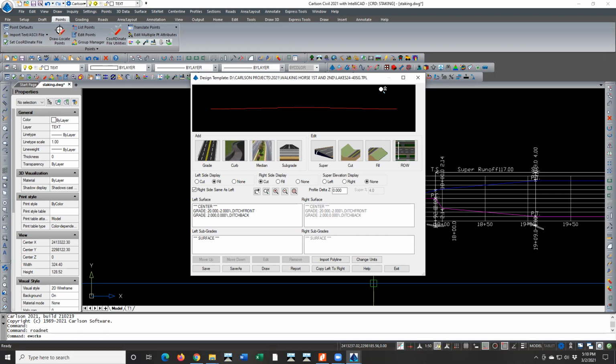Now my approach to all of that would be I would build the entire road itself and then output each one of those individual things, and I would make individual surfaces for those. And again, I was asking you a little bit about Surf-CE since you don't use it, and I'm not trying to push Surf-CE on you at all, but my approach was that Surf-CE can take that entire road file and separate out those individual surfaces as I choose to do my slope staking.